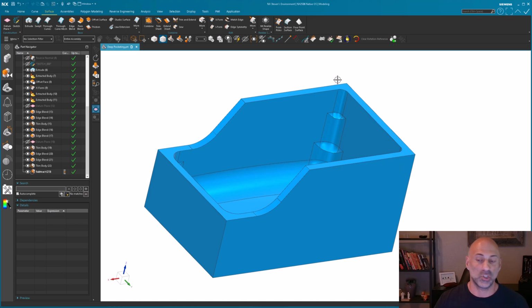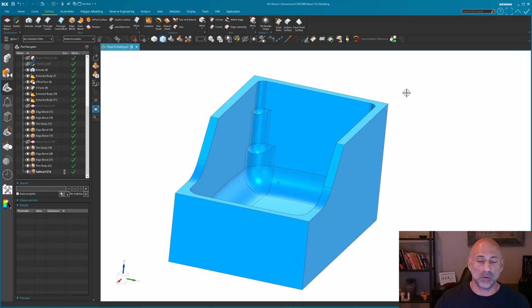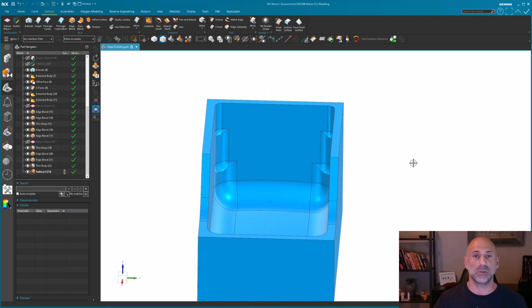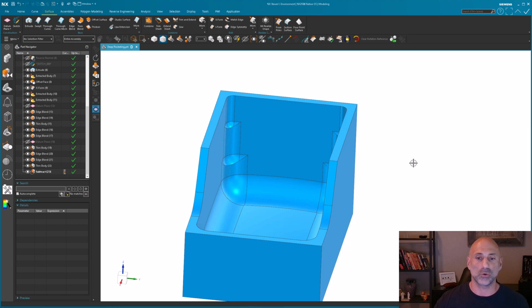And again, you can shave a fair amount of weight off of a part by doing these various steps. Again, you may have one additional step, you may have 2 additional steps. I don't see really anything greater than that. Again, it's for extreme weight savings, which could potentially be the case for whatever you're working on. So deep pocketing, weird faces, contoured surfaces, ball corners, the works. It's very important you pay attention to the driven corners and just basically all those kinds of concepts when you get into this type of machining.